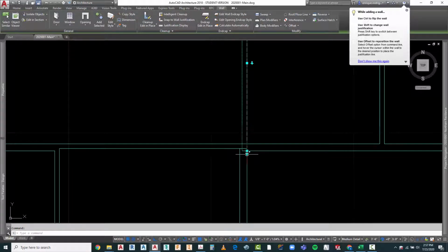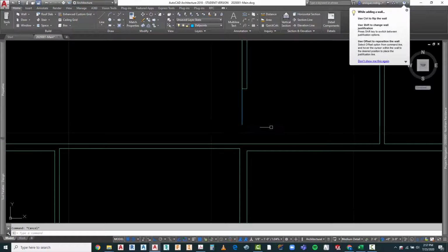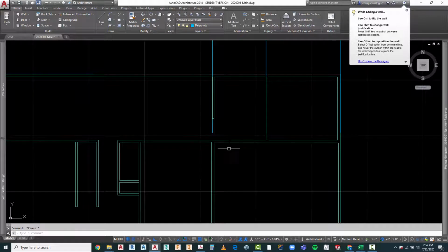And this one's going to fall a little short because we're going to get a hallway to come down in here, so no problem there. And then it's telling me that our wall, the horizontal wall here to create it, is a total of 7 foot 10 1/2. I'm going to change that to 7 foot 10.